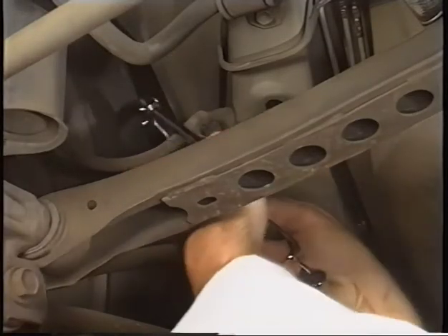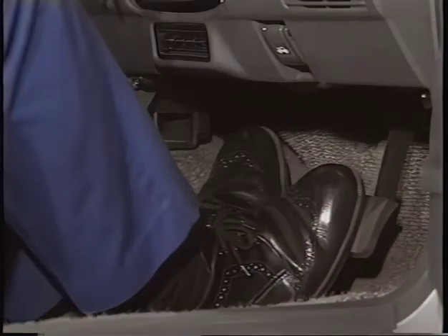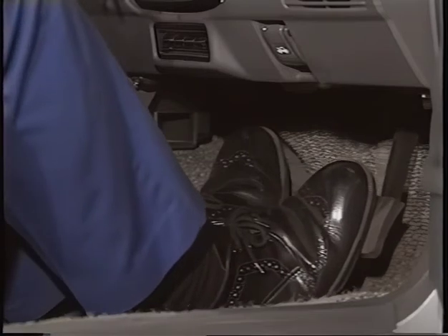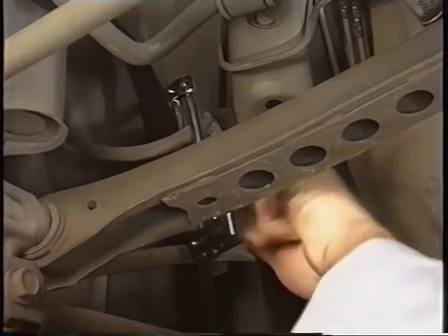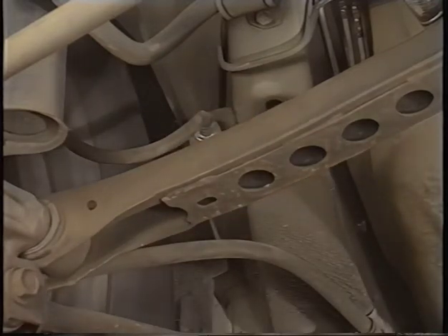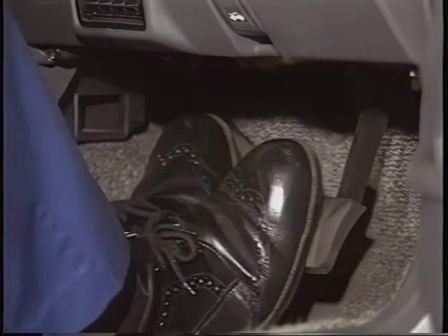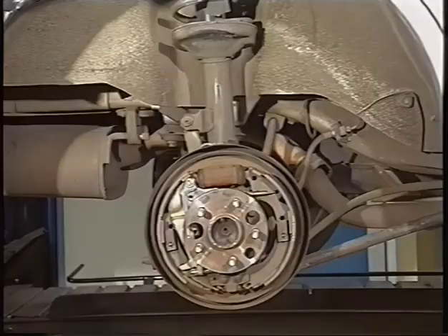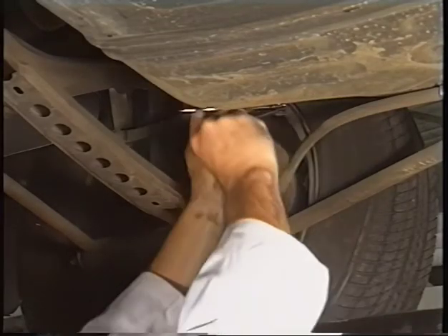Following this, all flexible brake lines should be clamped off using proper brake hose clamps. If the brake pedal is found to be high after doing this, the fault will lie in one of the service brakes. The wheel or wheels causing the problem can be identified by releasing one hose clamp at a time and checking the amount the pedal drops. Whilst the pedal should drop a small amount, a large reduction in height will indicate a problem which will need checking. It is most common for low pedal problems to be caused by the rear brakes, especially those systems with drum brakes at the rear, and is the reason why it is usual to release the rear hose clamp first.